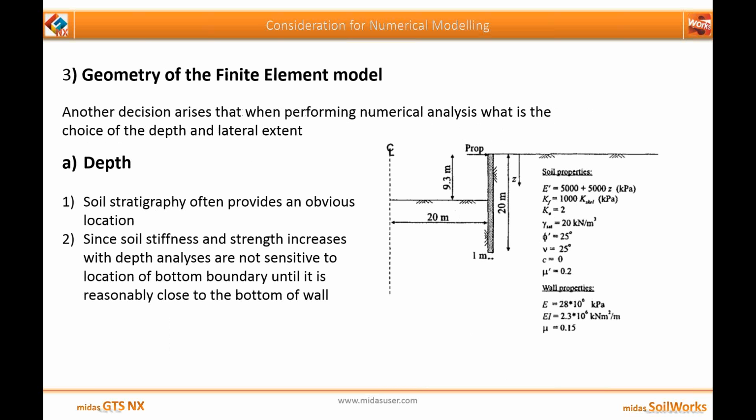Third is the geometry of the finite element model. Another decision arises when you perform the numerical analysis: what is the choice of depth and what is the lateral extent? So what will be the model size which will be accurate enough to give you proper results? First of all, talking about depth, soil stratigraphy often provides an obvious location. For example, if you have hard rock at a particular location, you can just stop and consider that depth as the model depth.